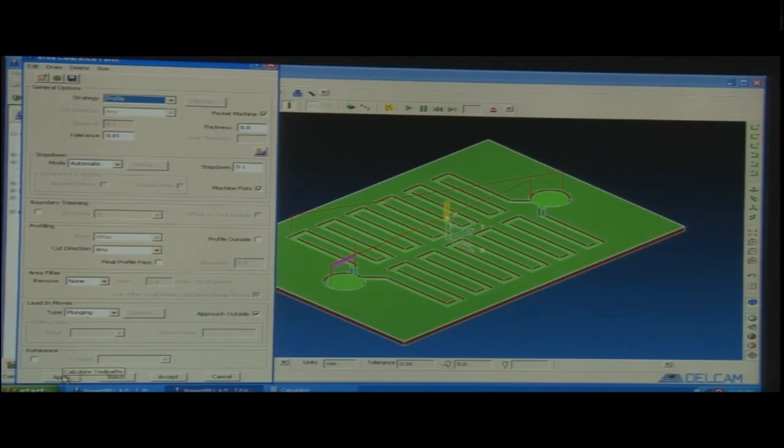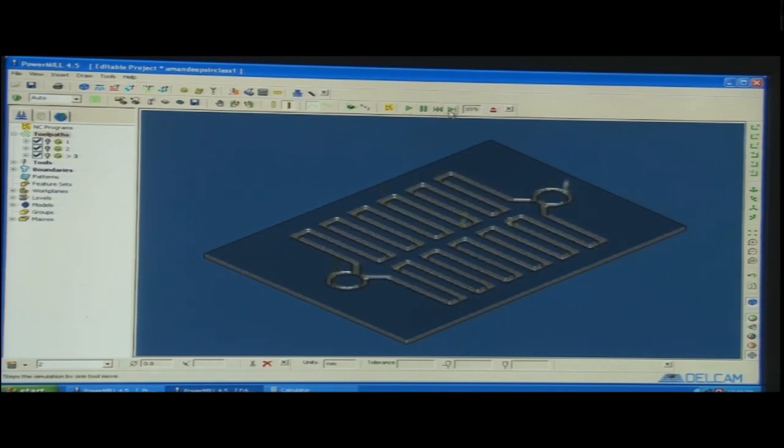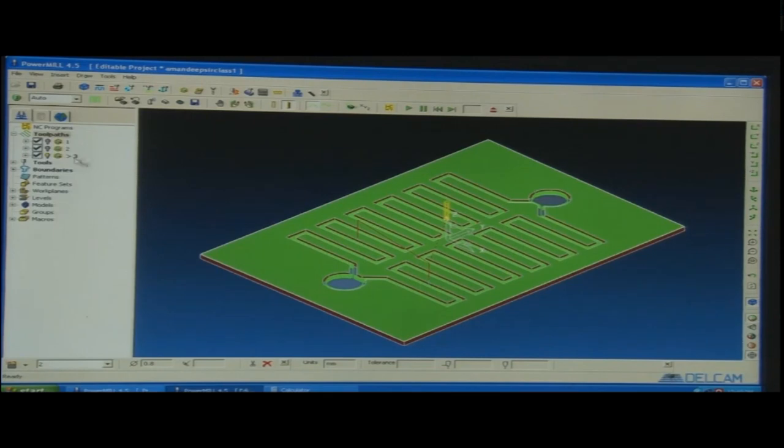Profiling is also one of the options. When we set profile here, how does profiling happen? When I say profile, it will machine in this way. You can see it will start from one point. It is just making a linear movement. This is known as profile or profiling. Okay, in one go, it has completely machined. So, it is not taking care of the stock, this round stock, the waste material that will come out. It just does the profile. So, roughing, profiling and finishing, the three modes.